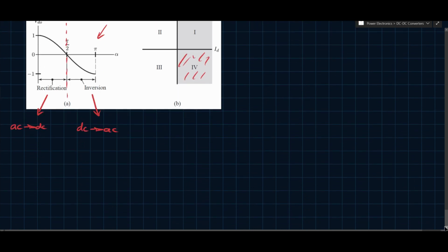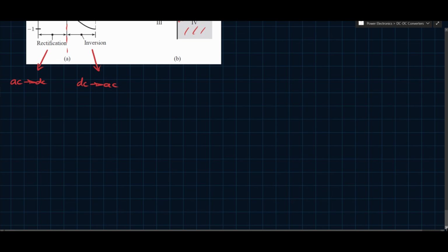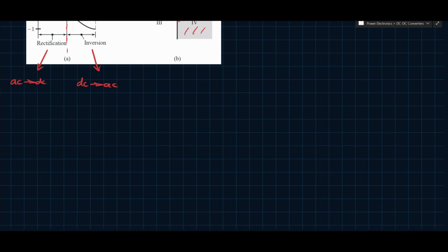So another thing we can do is take this one step further, and look at the concept of phase control, but with an AC side reactance. We did this with the full bridge as well. We called it the commutation reactance, right?